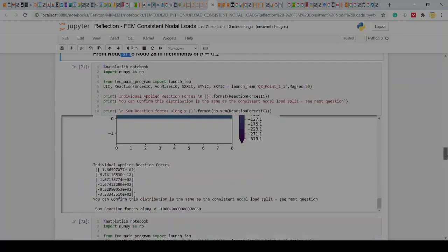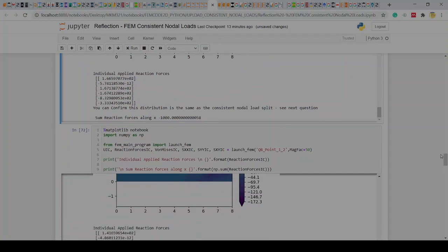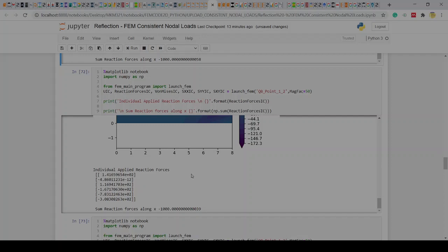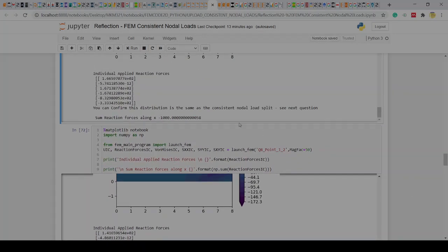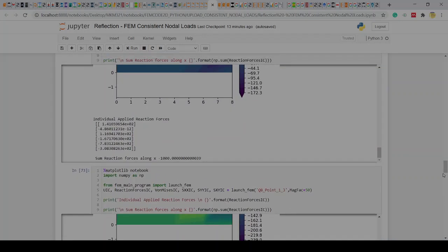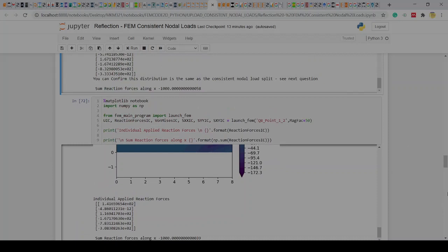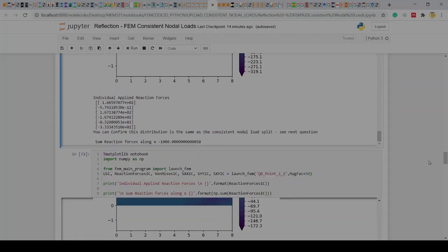I just want to show you the responses that we get. If I do that, this is the one that we've computed already, for eta of 1, so that's at the top. Then for eta of 0.8, we get these values here. We're going down from 166 to 141, still 0, 167 goes down to 116, and 167 there. Then minus 83 going down to minus 78, minus 333 down to minus 308. We know that this one is just at a node, nothing funny. This is the one that's off a node.